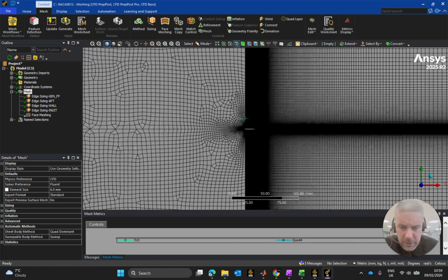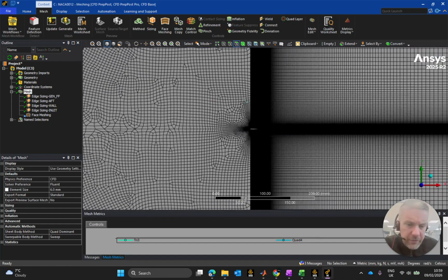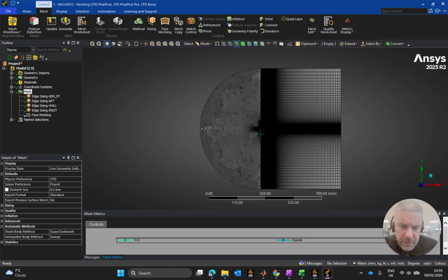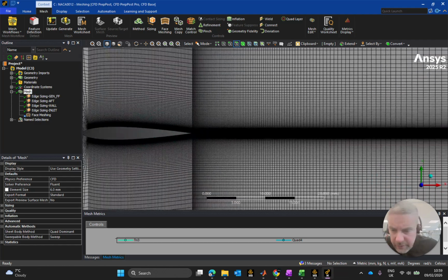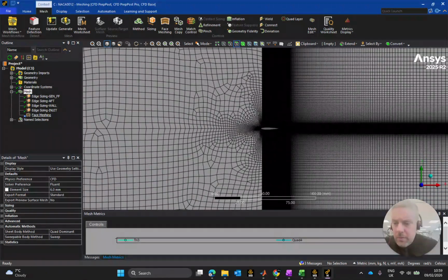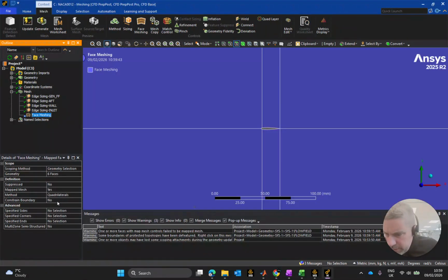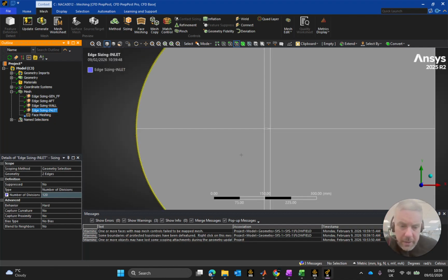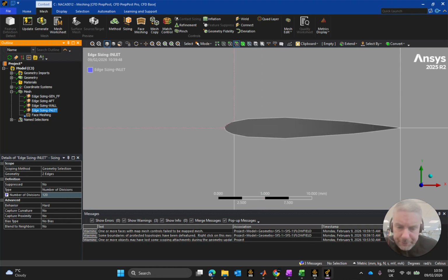So we're missing something in here, and this is generally what happens if you have selected not to, or you've selected to use blended face meshes. Let's see if we can figure that out. Let me just look in at the airfoil itself. Alright, looks okay. Face mesh. We have selected quadrilaterals on each one of them. Let's just take another look at our inlet size and blend to neighbors. No. Oh, right, gotcha now. Right, I didn't select my 2 faces here.